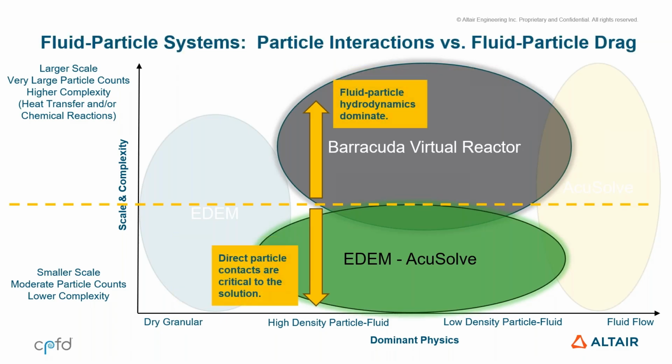And so when you study the medium to small scale systems, the particle contacts can be resolved with EDEM. And if these interactions are critical to the solution, like fluidized beds where the particle to particle interactions are critical, or systems like a combine harvester, where you have regions where the particles are agglomerating at a certain location, so there's accumulation and the contact forces are critical, and you need to accurately resolve these particle contacts, definitely EDEM AcuSolve is a solution for that. But when you have hydrodynamics as dominant, Peter will talk about that particular case.